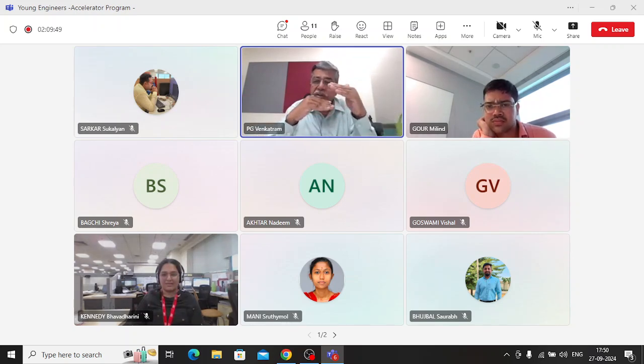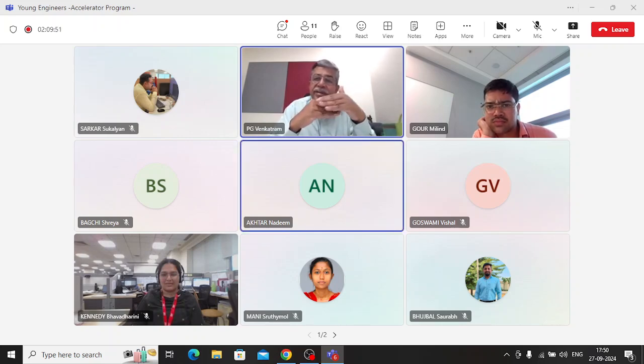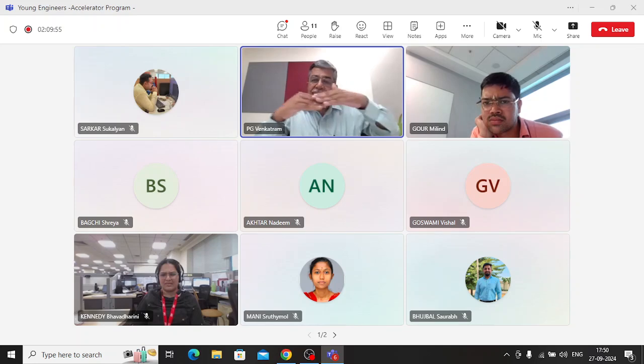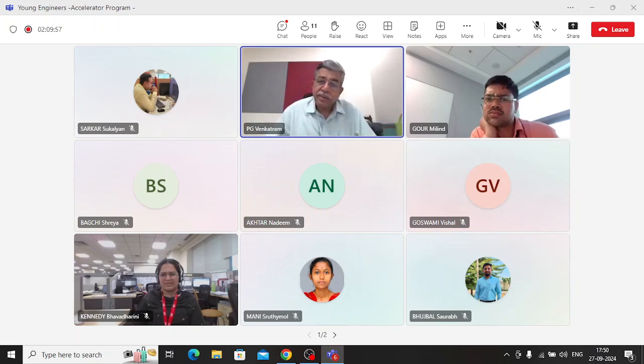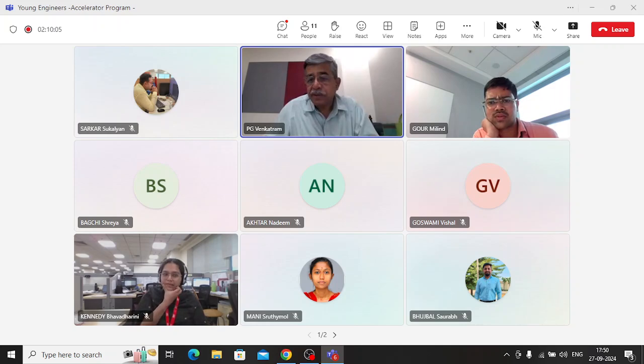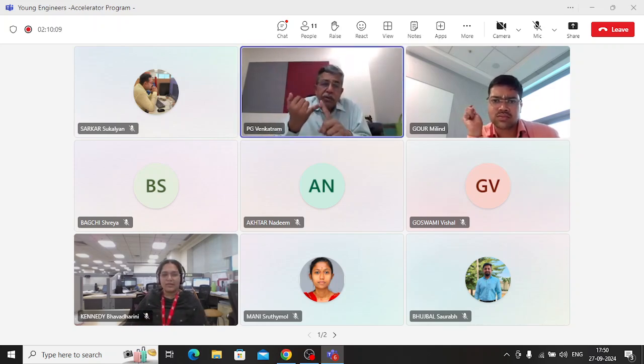Because PTFE and stainless steel have very low friction, the movement, the deformation will not get translated to the bearing, but the rotation of the deck will get transmitted to the elastomeric bearing. Vertical load definitely will get transmitted to the elastomeric bearing. So there are two ways to use elastomeric bearing: vertical load and rotation only, or vertical load, translation and rotation. You can use it in both.